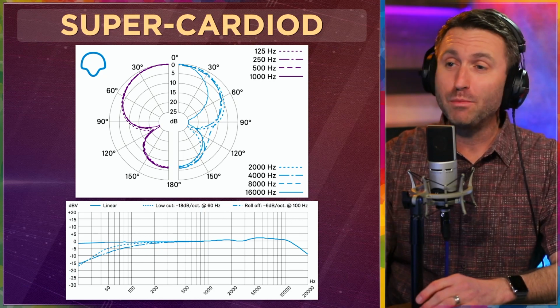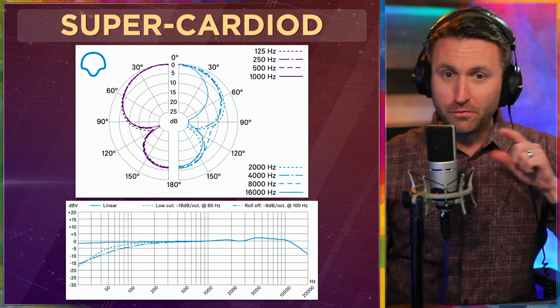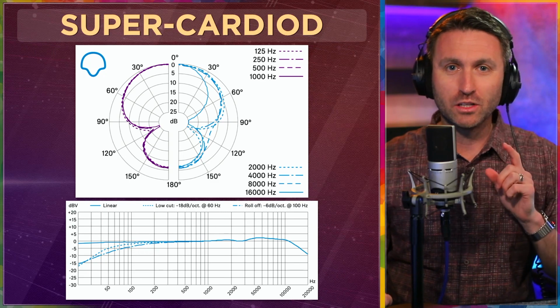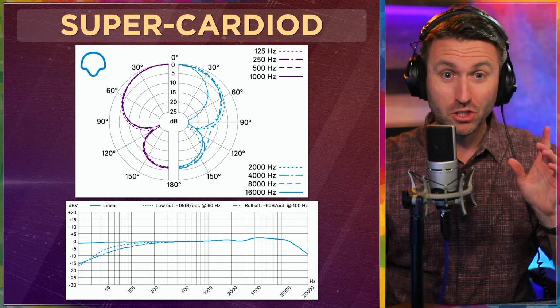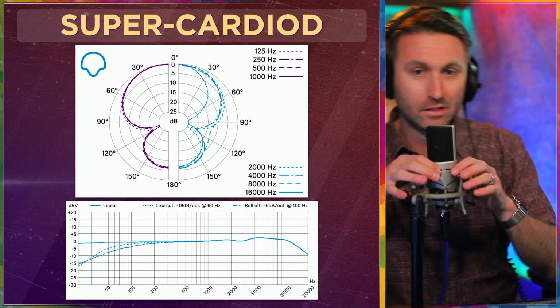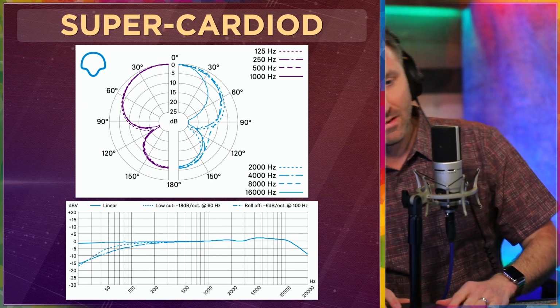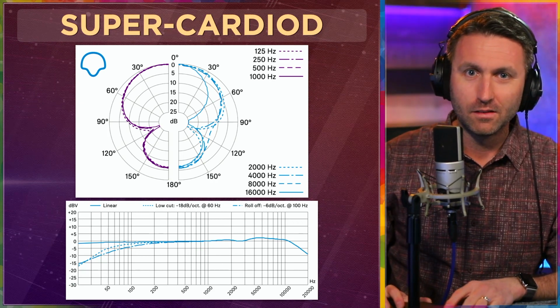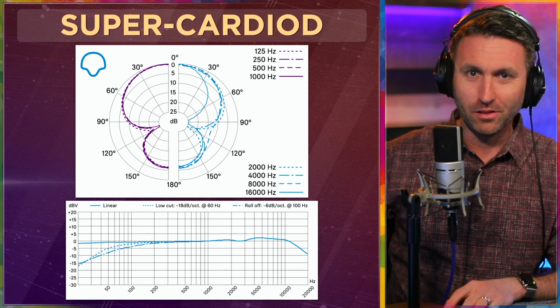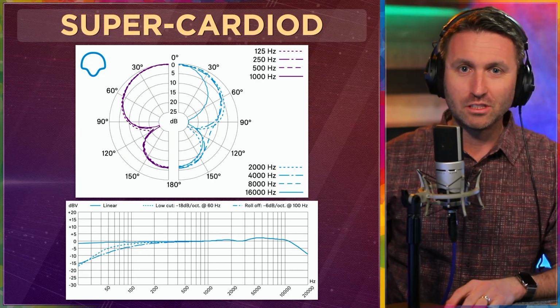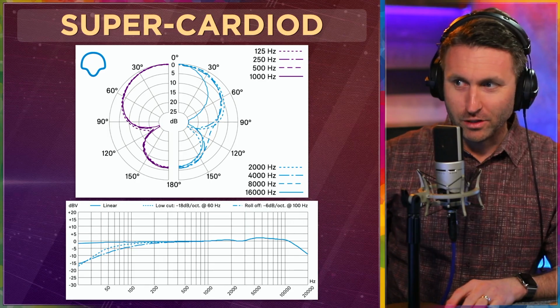Now, watch me do the quick A/B here. We're on supercardioid. It's the most focused polar pattern there is. Let me quickly switch to circular, to that omnidirectional. Let me show you what that sounds like. Same crowd noise here. Ready? Now you can hear a lot more of that. Now my voice is competing with that crowd noise because this microphone is picking stuff up from all directions, right? So it's harder for my voice to compete with that. Clearly, it's just not cutting through the same way.